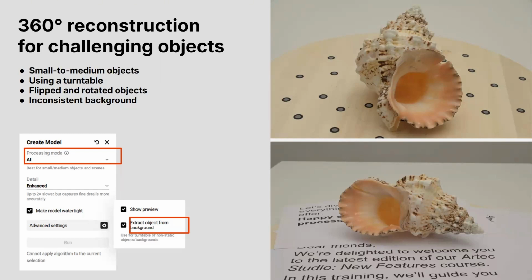In those cases, when you're either using the turntable or flipping your object using multiple orientations, we recommend the AI photogrammetry reconstruction mode with masks. You can enable it by selecting the AI processing mode, and then checking the extract object from background option.